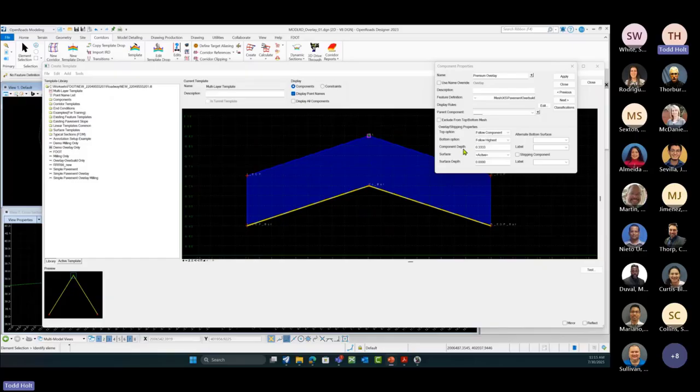Again, we want to think about the pavement design of what we're bringing. So maybe we are going to mill back or overlay back with premium of 1.5 inches or 2 inches. And then whatever is more expensive or less expensive, we can minimize that or have two different types of components in there.